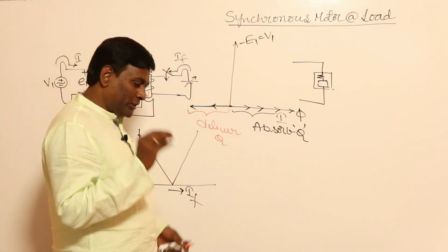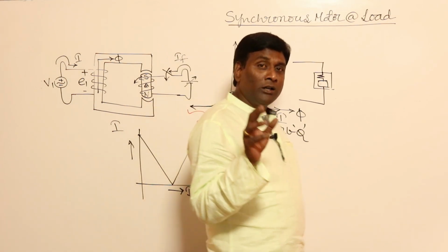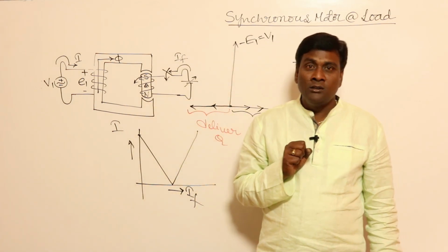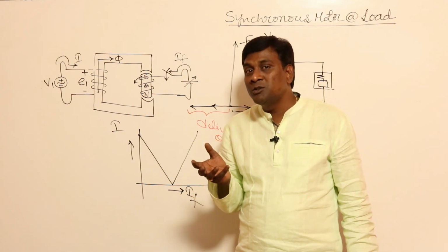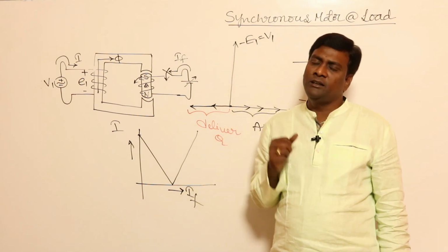Now one thing let me tell you: the motor absorbs reactive power when operating at lagging, and delivers reactive power when operating at leading. That's clear.